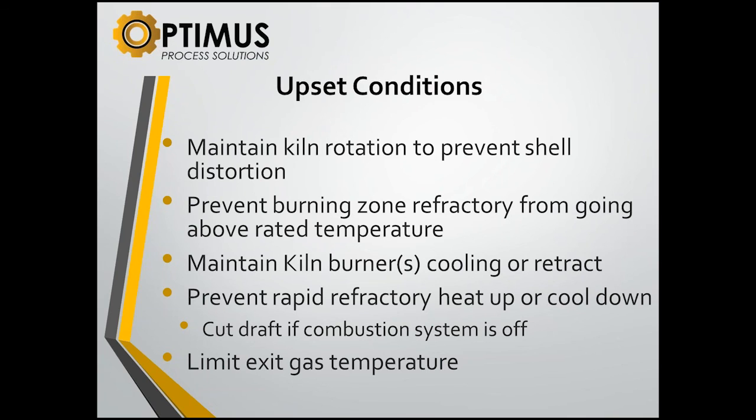Prevent rapid refractory heat up or cool down. I mentioned bottling it up, cutting the draft of the combustion system off. Also watch to limit exit gas temperature.